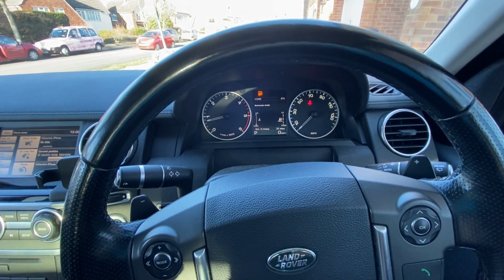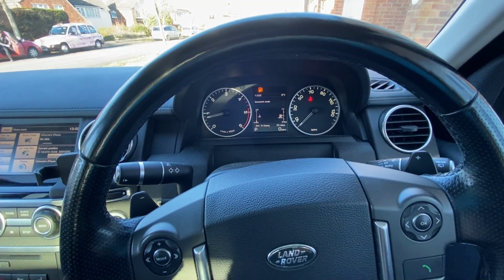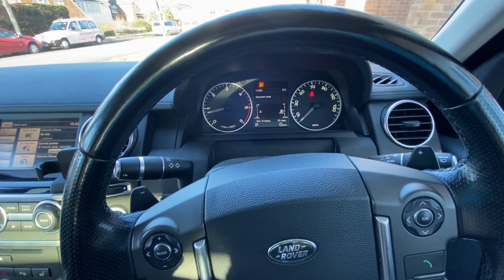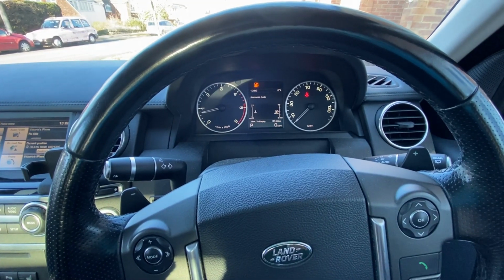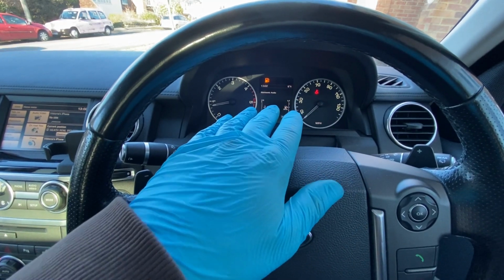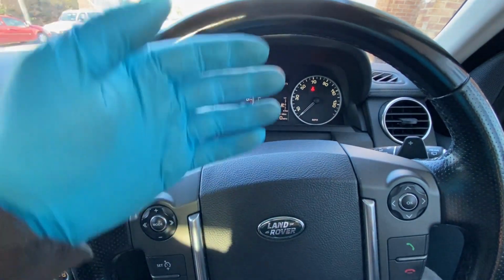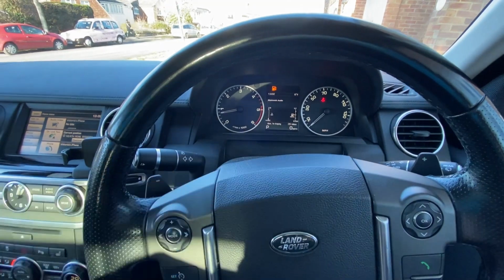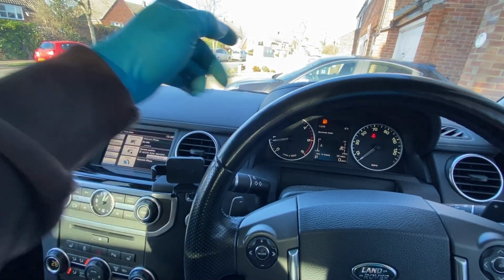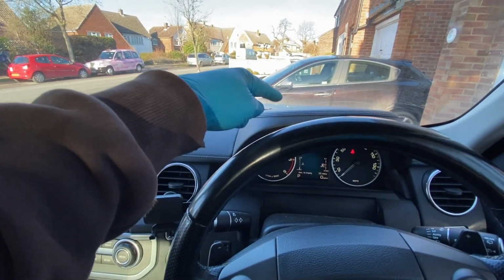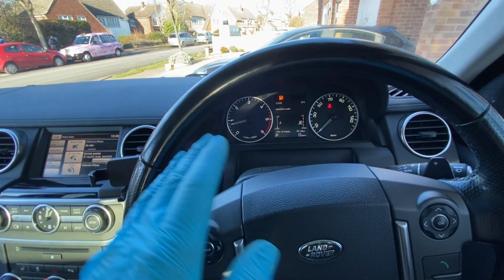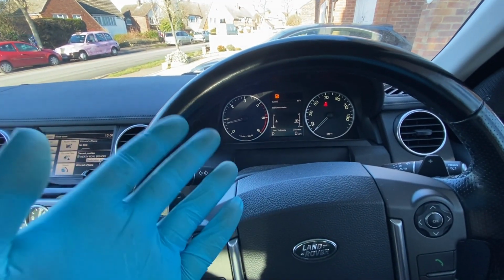Okay, and we also did the TPMS system there as well, just to go in and interrogate it and have a look. We went part of the way through the operation, but we then didn't go for a drive because I've not got the time today. But what it did do was, where it said that it will control the ignition and everything else, it did exactly that. It turned the ignition on, the steering wheel came in, out, up, down, and then I think the boot unlocked, the wipers came up and stopped halfway up the screen, the headlamp washers went one in turn, everything kind of went one at a time, that the car was obviously communicating and doing things to the car.